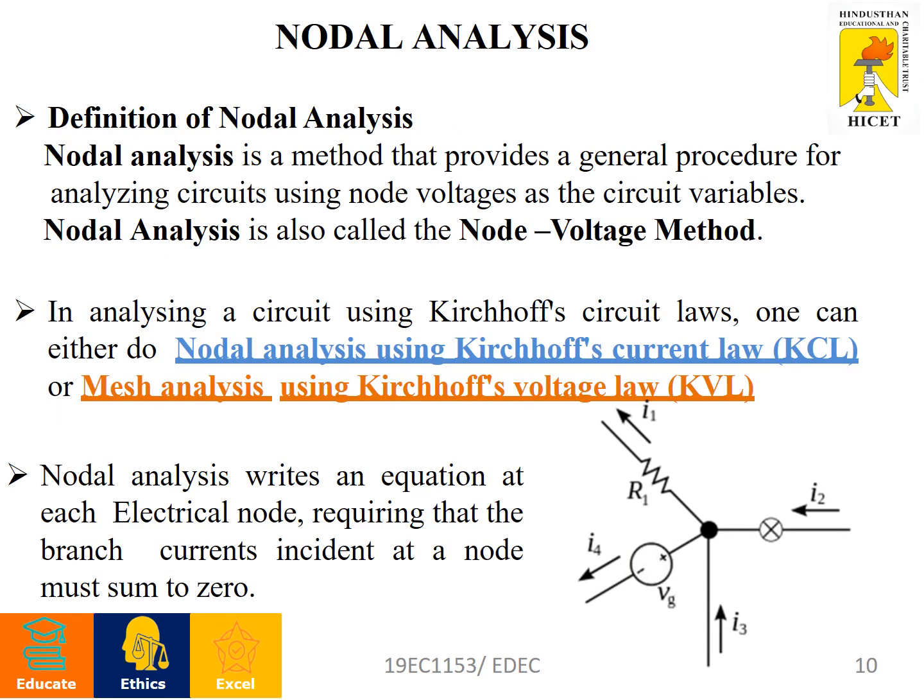The next one is nodal analysis. Nodal analysis is a method that provides a general procedure for analyzing a circuit using node voltage as the circuit variable. Nodal analysis is also called the node voltage method. For analyzing the circuit, we can use Kirchhoff's circuit laws. One can either do nodal analysis using Kirchhoff's current law or mesh analysis using Kirchhoff's voltage law. Nodal analysis writes an equation at each electrical node requiring that the branch currents incident at a node must sum to 0.